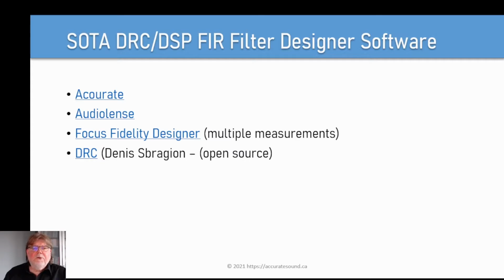On the topic of watching movies using transfer functions with time delays, most video fans I know will rip the Blu-ray or DVDs to MKV format and then use JRiver to watch the movie, as the video engine is aware of the FIR filter latency and will compensate so lip sync is perfect. If you're streaming video, then as a last resort, one can apply a frequency correction only and forego the excess phase correction. While the bass may not be quite as clear, it will be even in response. As you may remember, we still have access to 32,768 graphic sliders that other DSP/DRC software do not have.